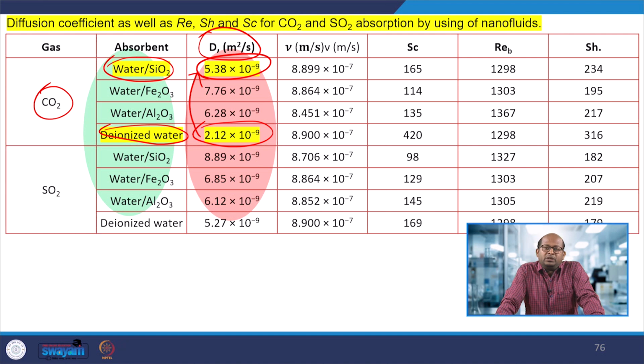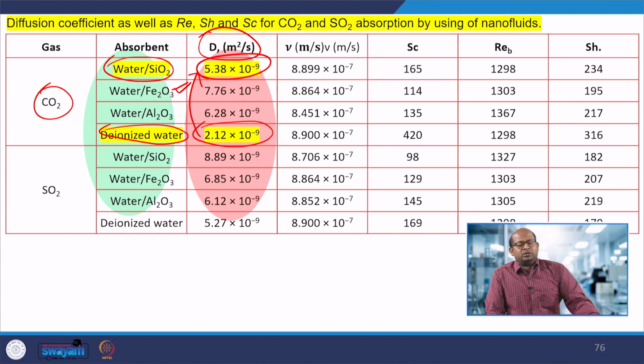So depending upon other nanomaterials also, the diffusivity of that particular component, that is CO2, in that fluid will be enhanced, meaning nanoparticles enhance the diffusivity and mass transfer coefficients for a specific operation for the separation of any component, that may be CO2 separation or oxygen absorption, or ammonia separation from any gas. So the base fluids and nanomaterials play a significant role in enhancing the mass transfer operation. So, thank you. Today is up to this.